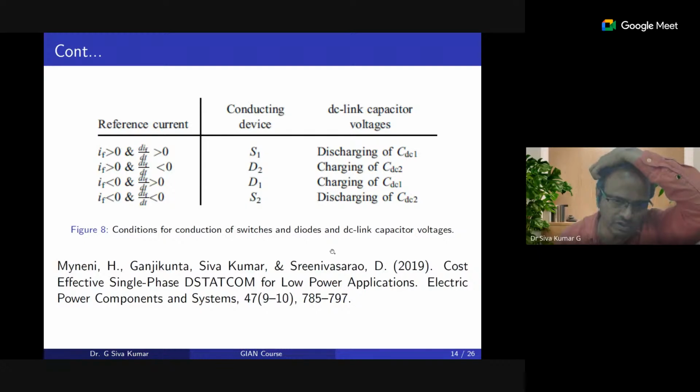In that case, we can use this particular compensator. It is used to eliminate harmonics as well as unbalanced current, and to provide reactive power support. In microgrid applications, one of the controls is the hysteresis current control technique, which has its own advantages. One of them is that we can avoid allowing short circuit current to the switches.